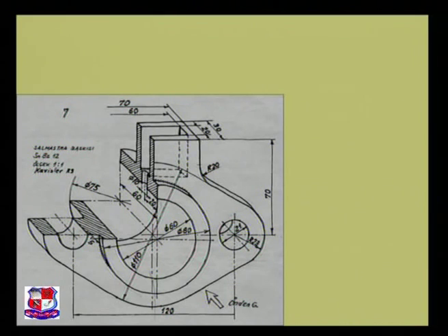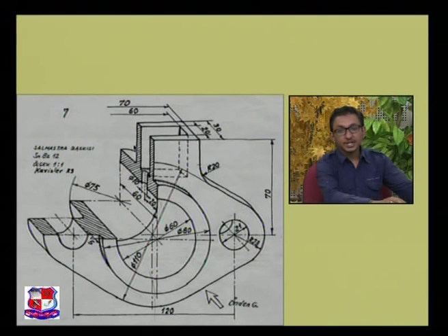It's a basic simple example of a technical drawing. As you can see in the drawing, various parameters have been given. The dimensions have been given. It's basically a drawing of a flange. As you can see, we cannot see the proper detail while this part is complete. So what we have done, we have just sectioned this part and cut down this section so that we can clearly see what is the inner thickness and what is the diameter of the circles.